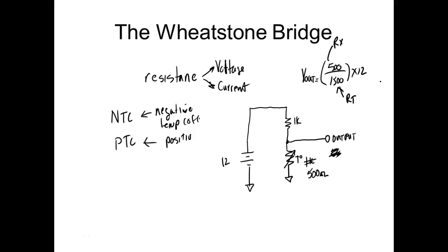It's really cool, because now you don't have to calculate current. So back in DC, you said, well, I want to find the voltage drop across this resistor. You add all the resistors together, you divide that into your total voltage, you get your current, you go back and multiply that back through to find the voltage drop. So what would this drop? I can mark off this guy, this guy, this guy, this guy, right? And then that 5, and that would be 1/3. So automatically, without even using a calculator, I know that drops 1/3 of the voltage.